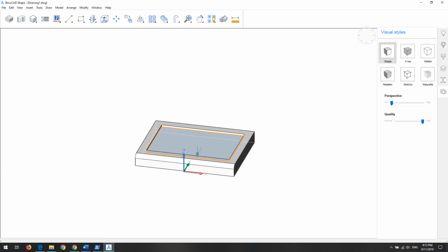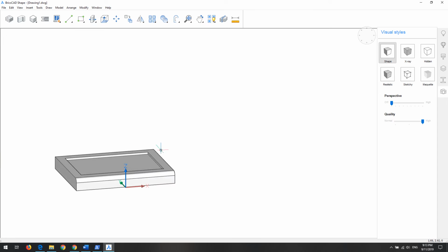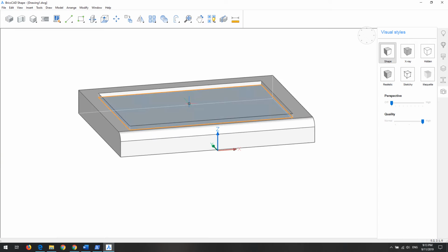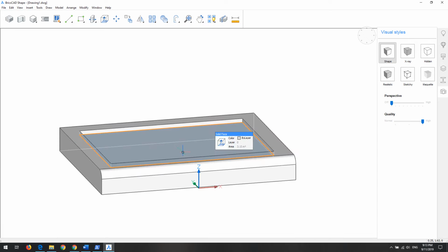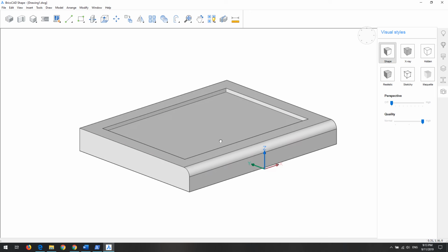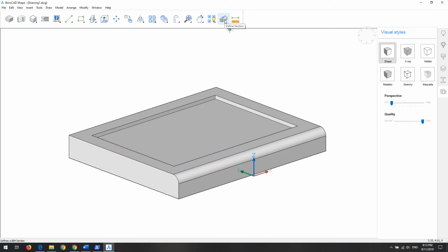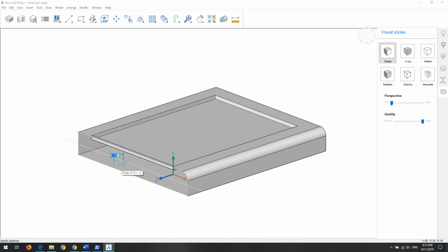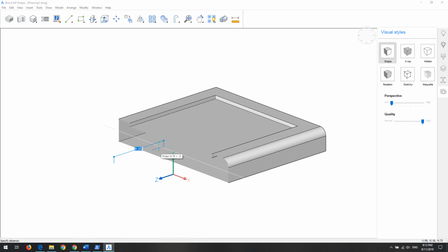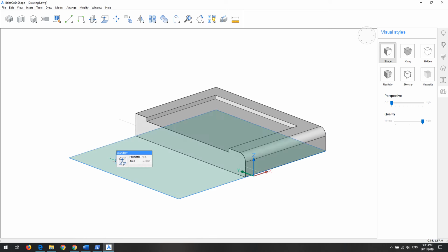Anyway, the beautiful thing about this software is that it is designed for modeling engineering things. You can easily see the cross section of this body using the define section tool, and you can hover your mouse on any face and then drag. Let's hover on this face, so the cross section will be created based on this, and then you can move the mouse and then left click.